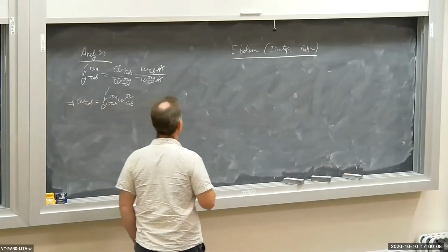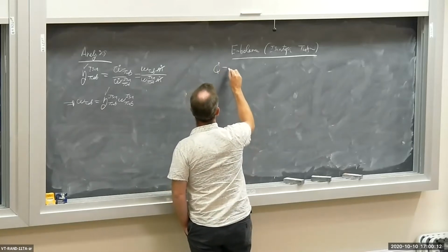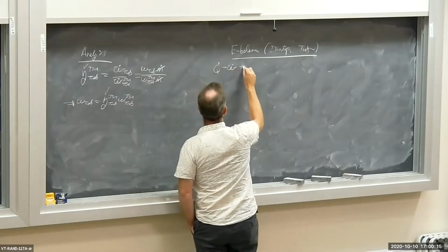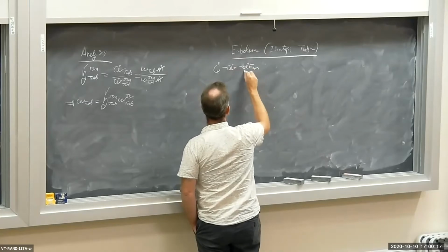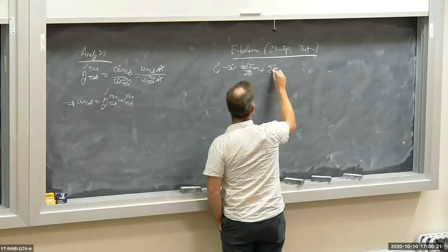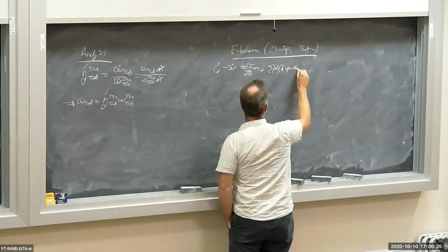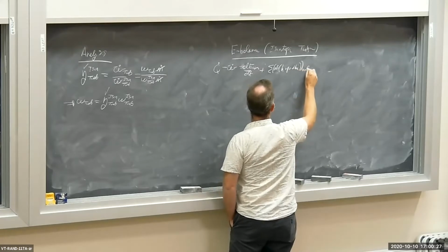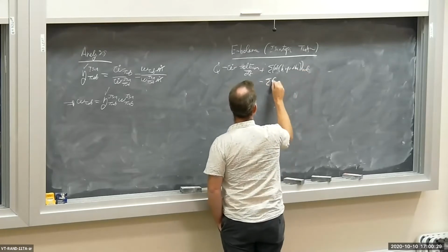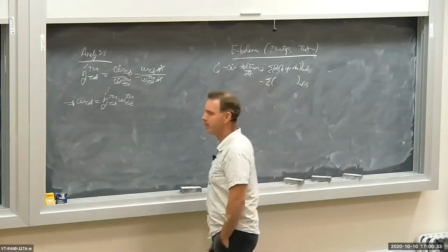Let's write out the energy balance. So we got Q dot minus W dot is equal to dE CV dt plus the sum of m dot (h plus PE plus KE) summed over all outlets. And then I got the same thing summed over all inlets, okay?